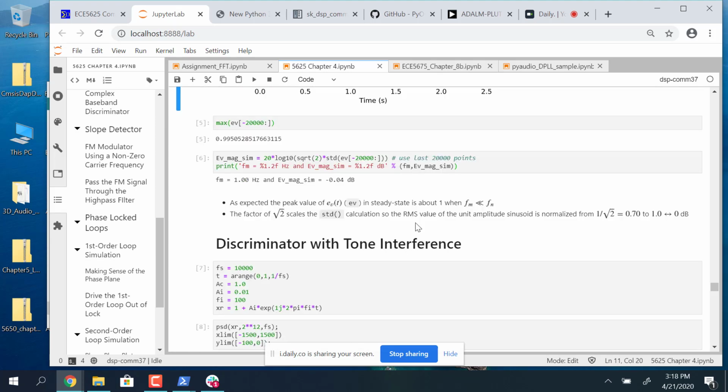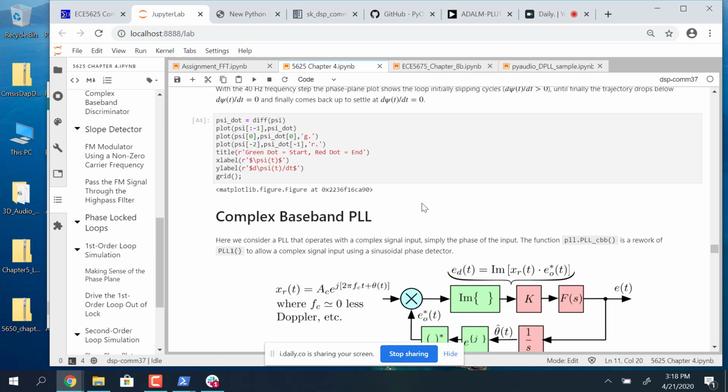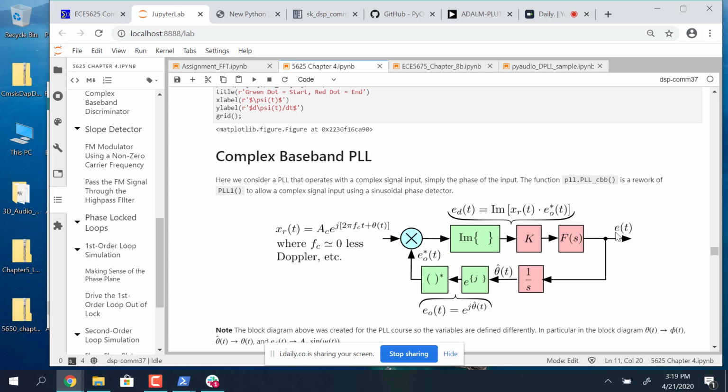So you'd be taking measurements here of E of t, and you'd want to see what that control voltage looks like as you change the frequency of the sinusoidal modulation, which is entering over at the input as theta through the waveform theta of t.